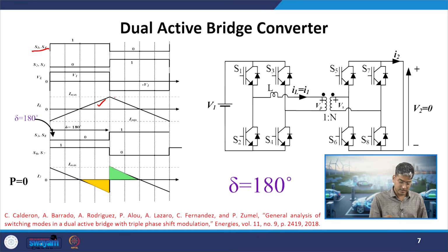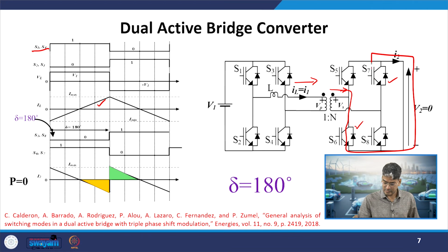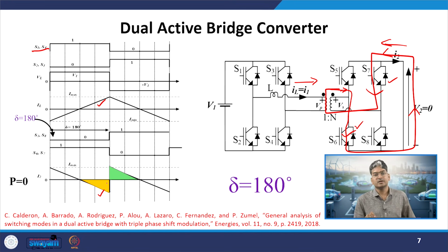Let us consider this as an example. From the dots we will find it out. Over here, the current is positive in the 4th division, and the switches that are on the secondary side are S6 and S7. With S6 and S7 on and my current positive, it is entering the dot, so it will try to leave the dot on this side. What will be the path for that? It will flow through this and back. So it has flown this way, and if you see, it is negative, because it is in the opposite direction of our measurement. The same thing we found from our conclusions.